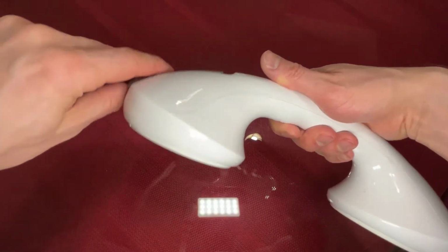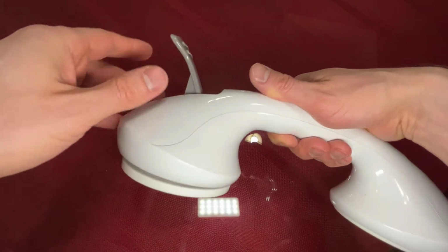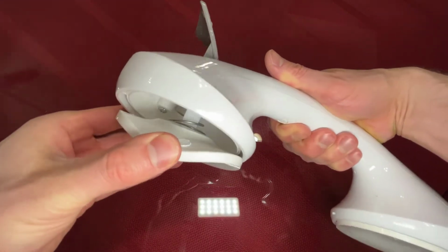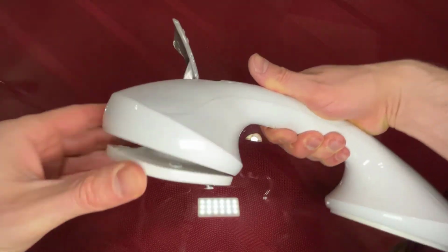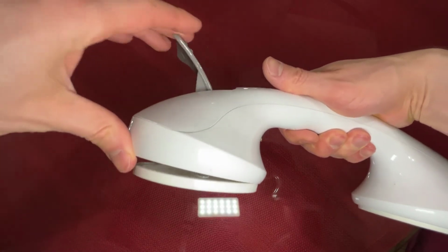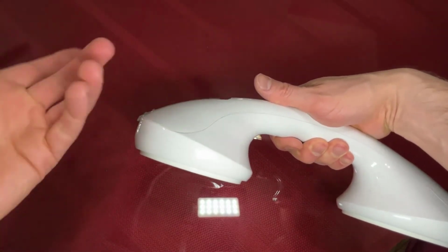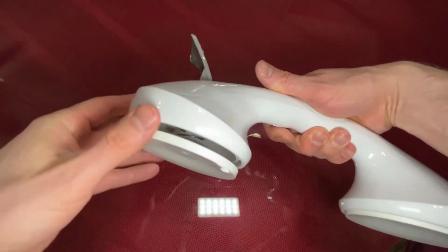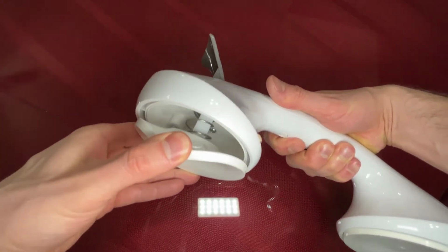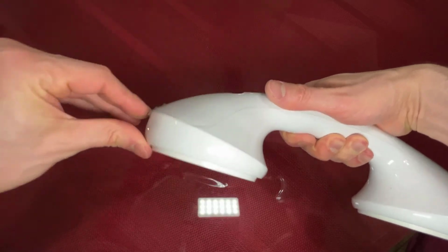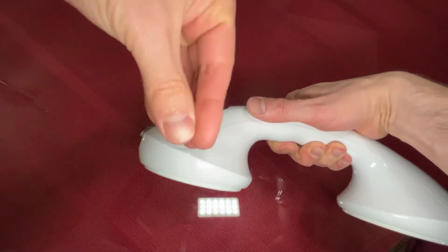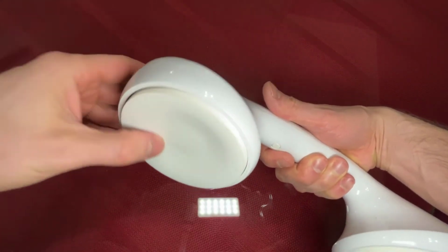Very simple cam mechanism. When you pull the lever, you can see the inside here. You have more room. When you pull it down, it moves the suction cup vertically in the Y direction. And let me show you what's going on inside. When you move it up vertically, it sucks the suction cup up, and that's what creates the vacuum here.